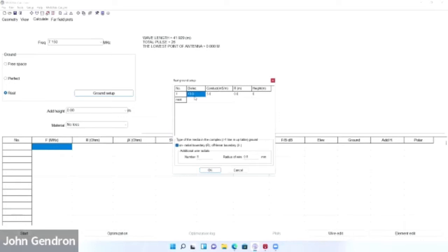Now, if I'm down at the coast, Myrtle Beach, the island, Hilton Head or on Folly, I'm going to increase that because your conductivity is 1,000 times more down at the beach. So instead of 5 millisiemens per meter, you're at 5 Siemens per meter. Okay, it's a big difference, and I'll show you that. But for our purposes, we're going to use 5 millisiemens for right now. So 5.0. Okay.